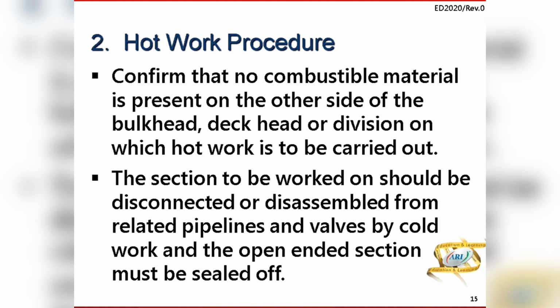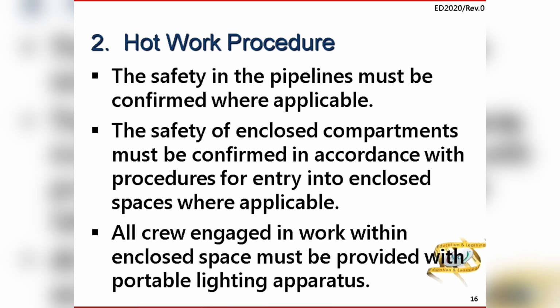The section to be worked on should be disconnected or disassembled from the related pipelines and valves by cold work. Cold work means you use brass tools to remove the nuts. You're not cutting, it's cold work. You're just opening the nuts. And the open-ended section must be sealed off. Safety of the pipeline must be confirmed where applicable. Safety of enclosed compartments must be confirmed in accordance with procedures for entry into enclosed spaces.